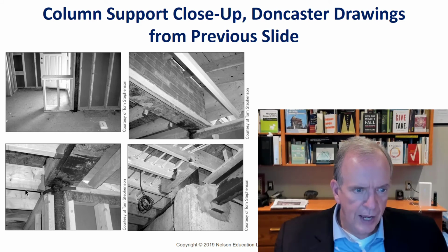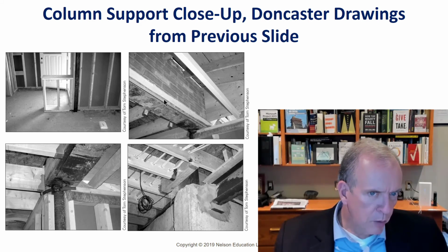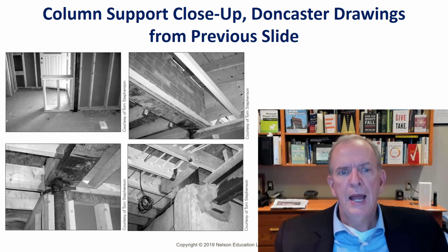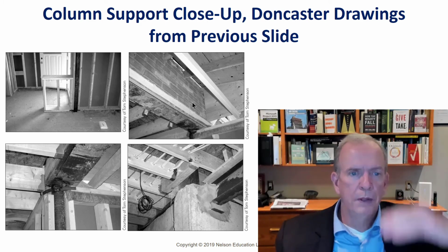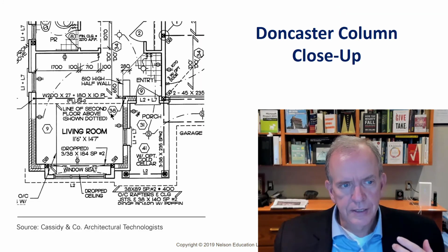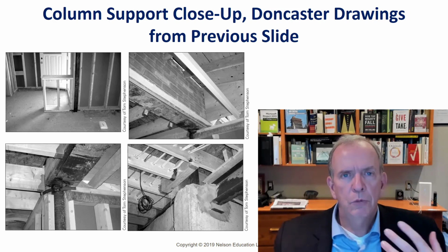This is looking at it from another angle. And you can see that 280 millimeter plate. You see how the mud stops here and the I-beam is up there? That's welded on this corner and on the inside corner there all the way along. And then that has the brickwork that's going up over top the second story, because the second story goes straight through, and this room sticks out only on the first floor. And so that leaves the ceiling inside to be open and flush when it's finished. So it's good to look at these things and envision these kind of things. And that's difficult for you right now, but over time it will get easier.